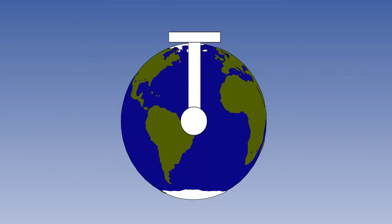This is why the pendulum analogy is popular. When we discussed platform stabilization in an earlier lesson, we said that the V/R feedback loop could be likened to a large pendulum with a length equal to the Earth's radius, with the platform bolted on at right angles. The bob of the pendulum remains at the centre of the Earth. Then, as the aircraft travels, the circular motion of the rigid part of the pendulum keeps the platform level.